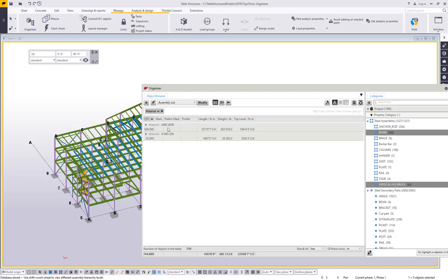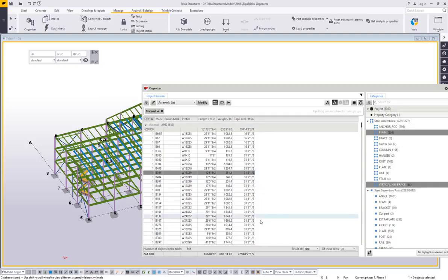If you see something that shows up as an A36 line and you only have beams and columns selected, right away that's a trigger to me that something's not quite right with this part. Let's investigate it further. So with that theory in mind of investigating further, what if there was one of these beams that I wanted to investigate further?